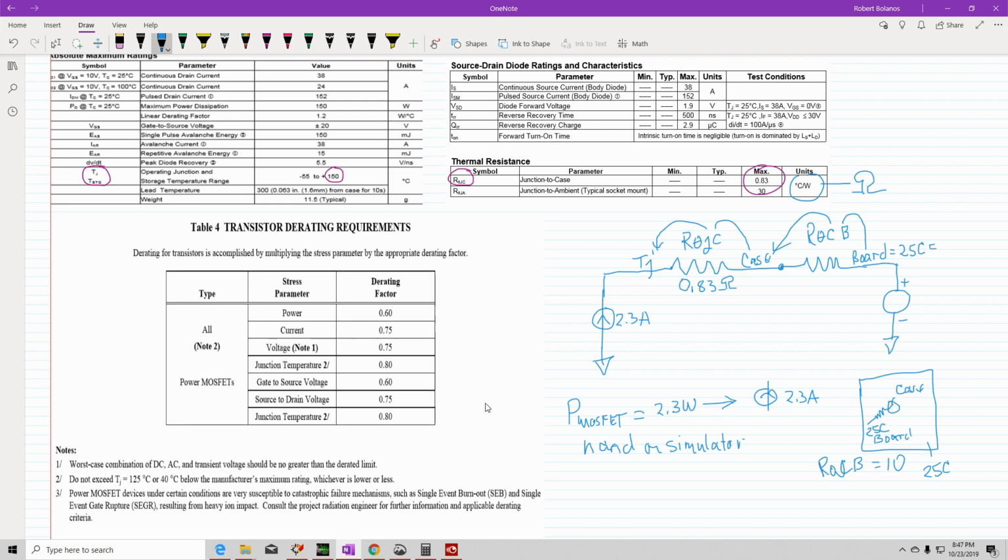Okay, now let's go ahead and change this to 0.1. And remember, yesterday I said that because we changed the windings, this drain will be swinging higher than 100 volts. So the internal diode that's inside will avalanche and act as a zener, and it will clamp it, and it will be conducting power. So let's go ahead and run it again.